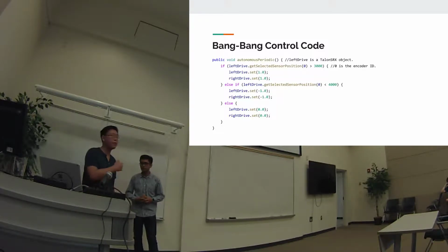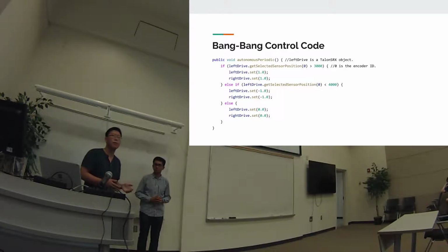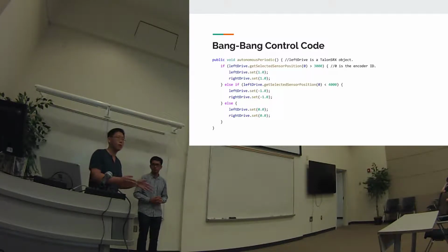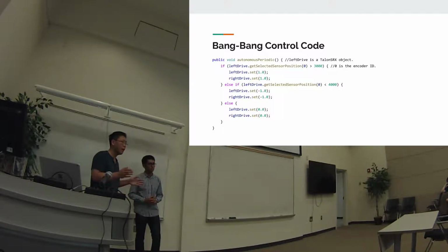Let's say you use this for a driving example again. Even though we're technically using a control loop now, just to move forward, it doesn't guarantee you're going to go straight, right? Because it only measures the encoder outputs. It doesn't take into account a gyroscope that might be on your robot, for example. Your encoders might reach their target position, but that doesn't necessarily mean you're going straight.